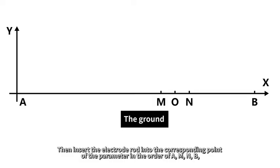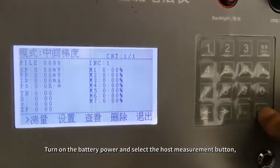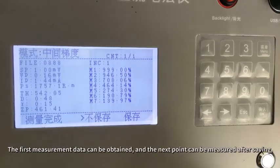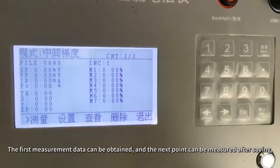Then insert the electrode rods into the corresponding points of the parameters in the order of A, M, and B. Turn on the battery power and select the host measurement button. After the instrument measures by positive supply, shut down supply, reverse supply, shut down supply, the first measurement data can be obtained, and the next point can be measured after saving.